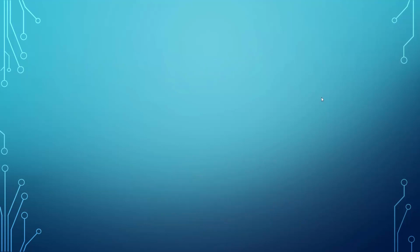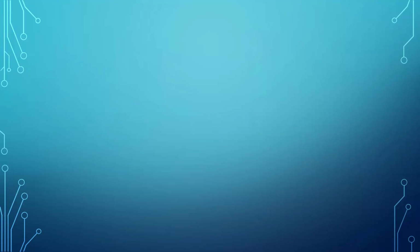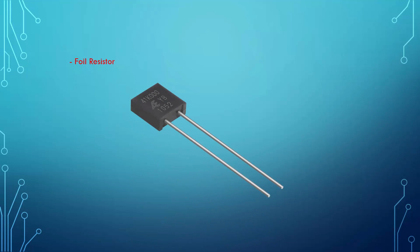The next is wire wound resistors. This resistor type is generally reserved for high power applications. These resistors are made by winding wires with a higher than normal resistance on a former. And the last one is foil resistor. Foil resistors have had the best precision and stability ever since they were introduced. Advantages of foil resistor are high stability, low noise, low capacitance, and low inductance.